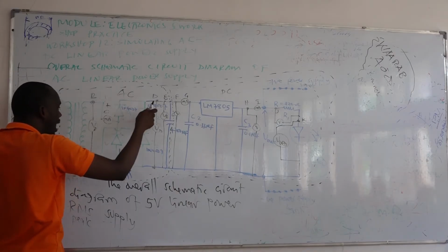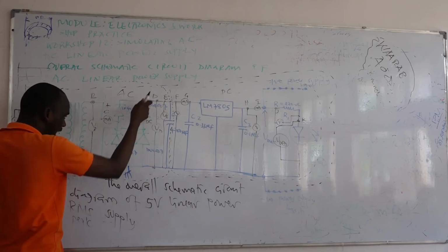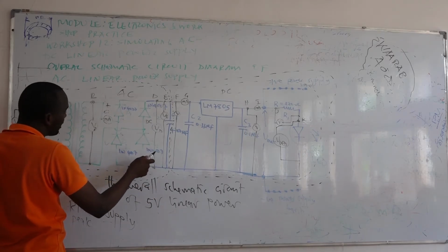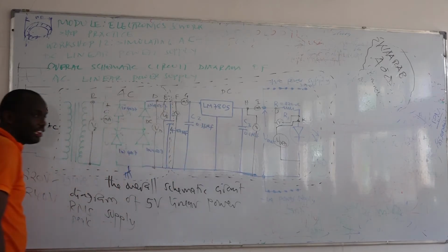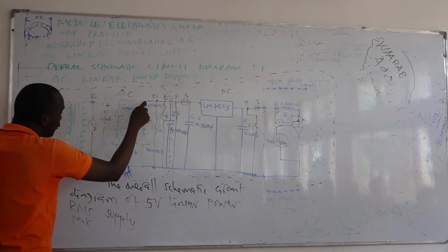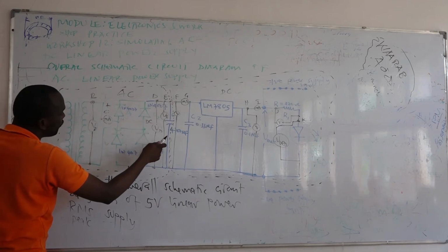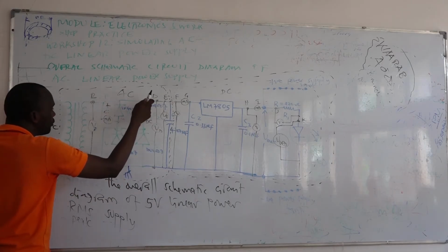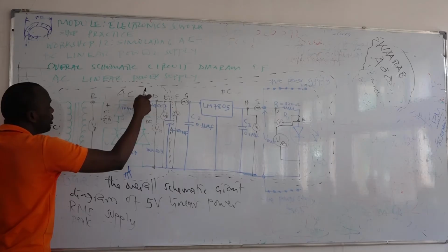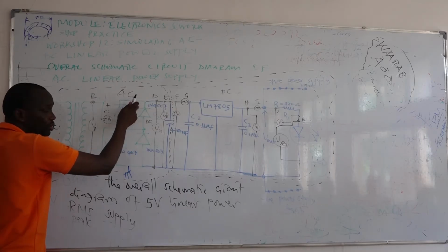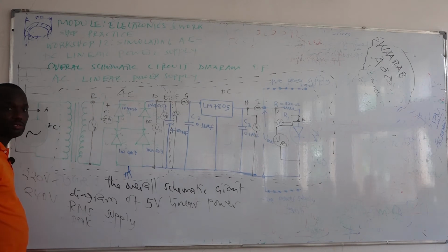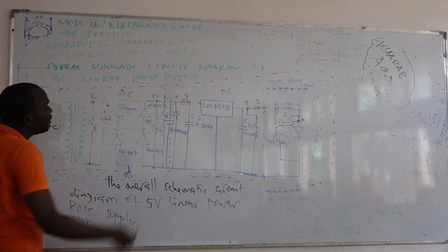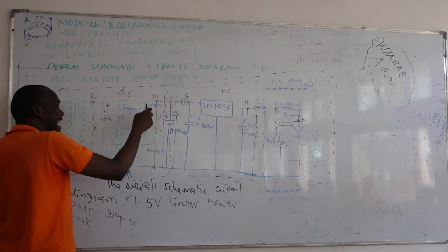Either that power might flow in this network through the 1, the 2, or the 4, through the 2 and the 4, or might flow towards this direction. So it won't flow through the 2 and the 4. Why? Because this is positive voltage or positive power. So positive power is connected with cathode, so this diode 2 will be in reverse bias. Okay? So if it is in reverse bias, here there will be high resistance.